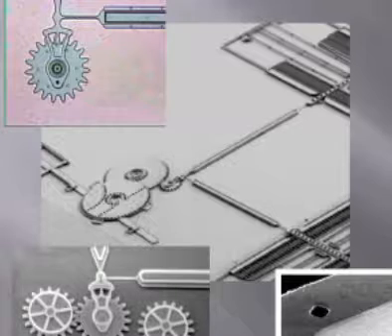You guys ever use oscilloscopes? Ever do Lissajous figures? You put one frequency in for Y and you get the sine wave. Then you put another frequency in for X. If the frequencies match, right, you get an oval or a circle depending on the relative amplitudes of the 2 signals, right, the voltages on them, right?